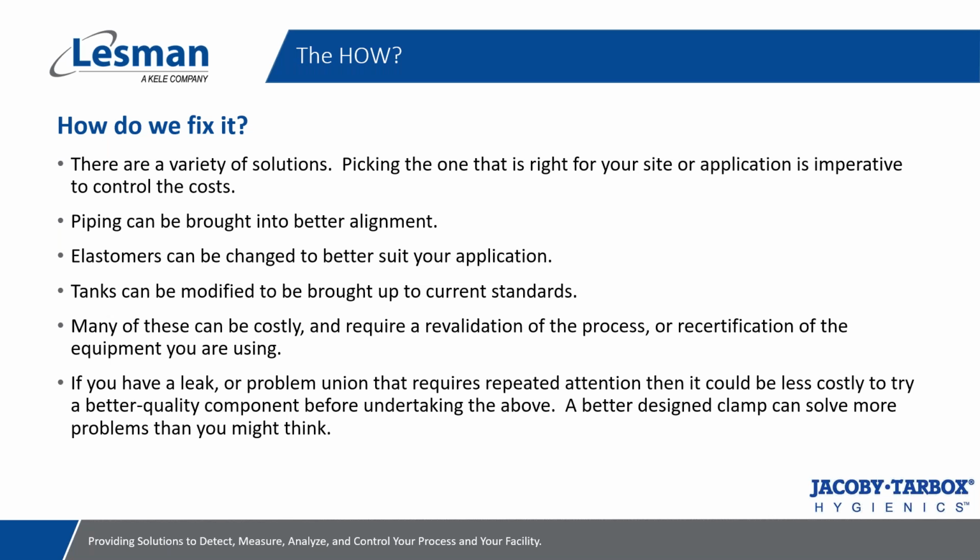So many of them can be very costly. They can require revalidation of the process. They can require recertification of the equipment, right? Chances are, if you need to make an elastomer change, that's a wetted component, and you may have to revalidate. This is why I stress to facilities